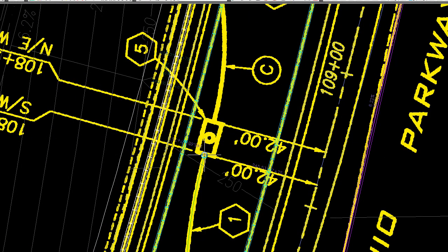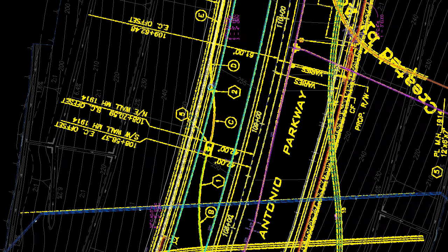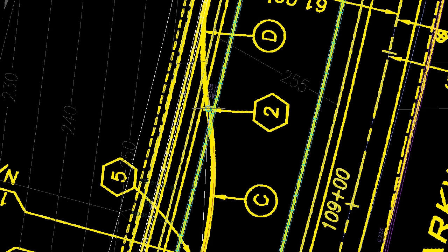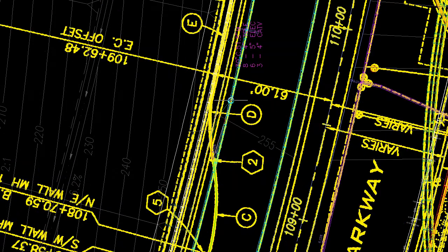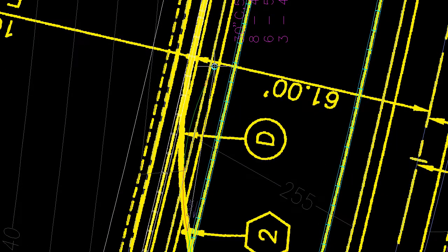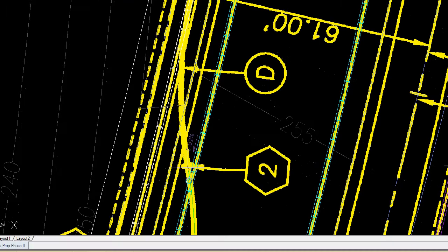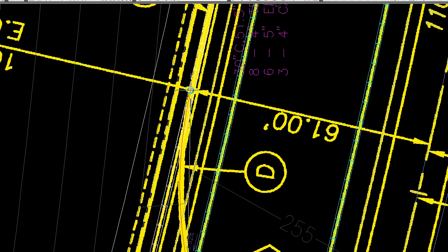Let's pull a straight line through that, go back to arc, and you can see that their drawings are nice. This image isn't stretched anything, it came straight from an electronic PDF. So this alignment is merging back in with this line over here, this joint trench. So I only need to draw it to right about there. Okay, so now I've got a polyline.